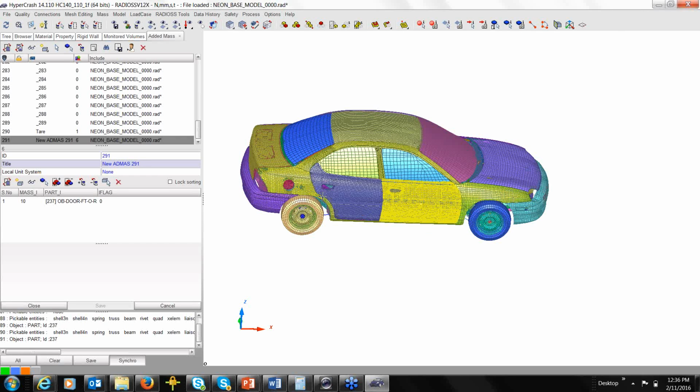So when you finish meshing your model, you need to check the mesh quality in HyperMesh, for example. You check the mesh quality, HyperMesh will calculate all the smaller size elements, and give you the smallest size element in the model. You can identify that. If it's a 0.1, you say, no, I'm doing an explicit analysis. I cannot manage 0.1 element size. I need to change that element size. But if you're, for instance, doing a really small model, like in this case, this model is probably closing in on more than 500,000 elements.